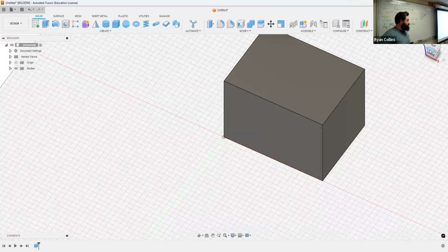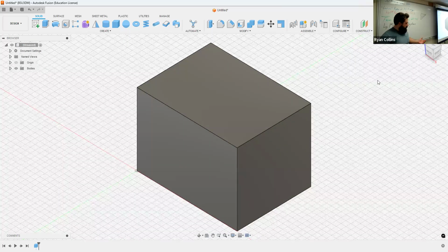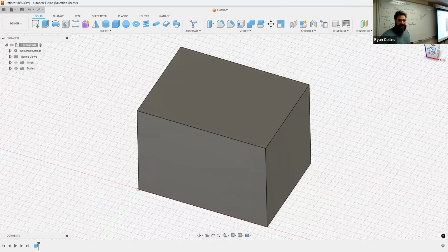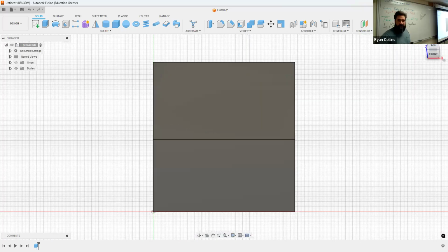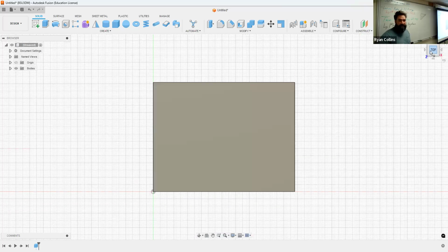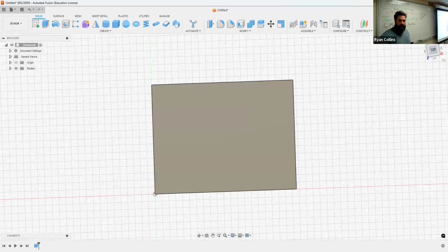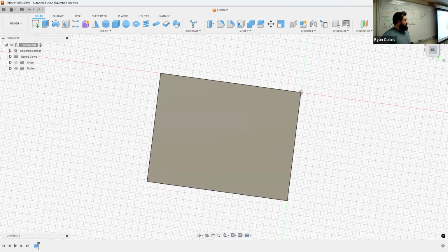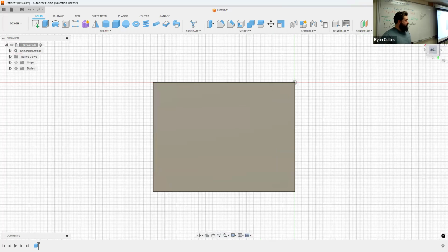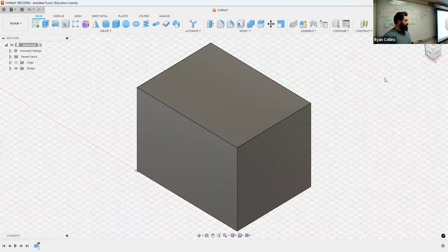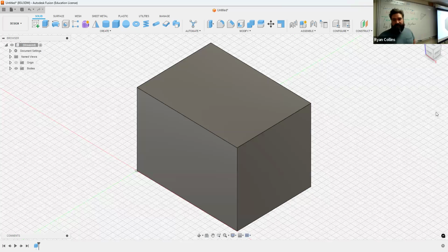I will often refer to the home button. When you mouse over it, you will see this little home symbol. That brings it back to standard 3/4 perspective view. You can also click on the sides and such of that view cube, so you can get partial views. If you're looking directly at the top, bottom side, whatever, these little arrows will show up, and you can rotate it. Like I said, Fusion likes to hide things that you don't necessarily need. That doesn't show up unless you are looking directly at the top or side view or something like that. That's pretty much how that works.